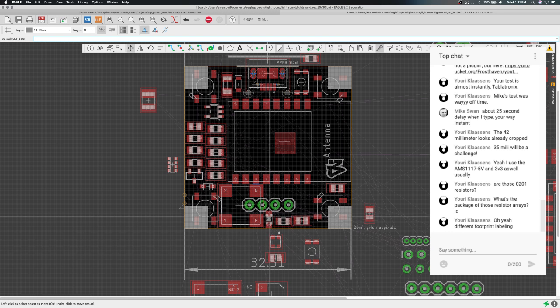And then I had the LED move down to here so that if you have a device or a cube or a light, the USB is in the back and then the light can be on the other side in the front. And then you could always light pipe this to the front. So even if you use this board without the NeoPixels, I could have it as a sensor node of a temperature probe, and just put it in a little case and have just the LED in the front. So I kind of squeezed this in here just to get it right in the middle.